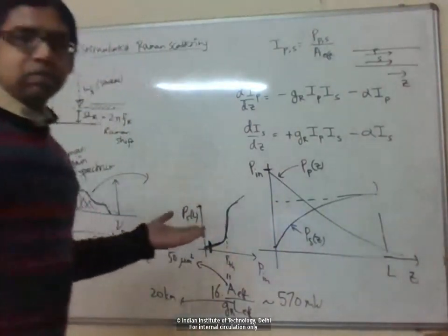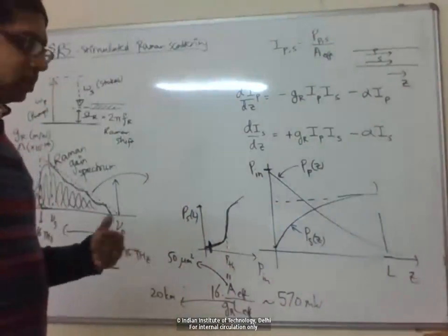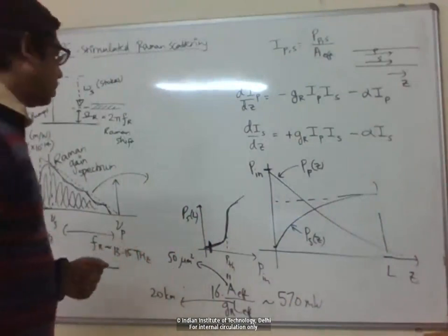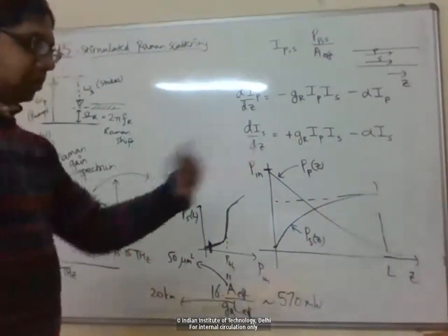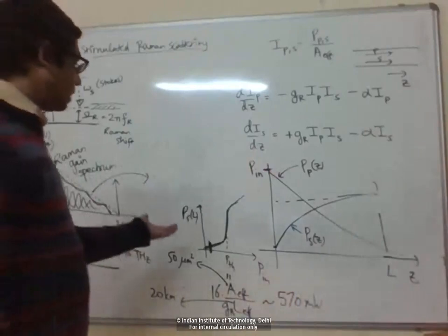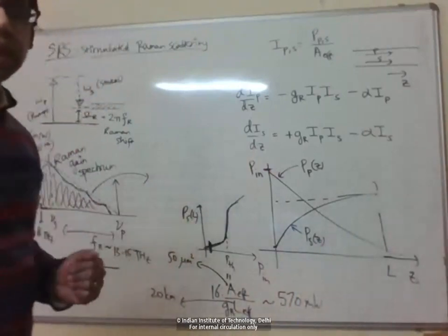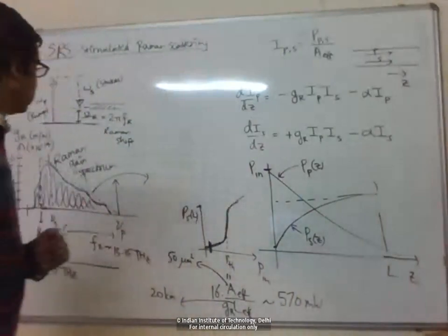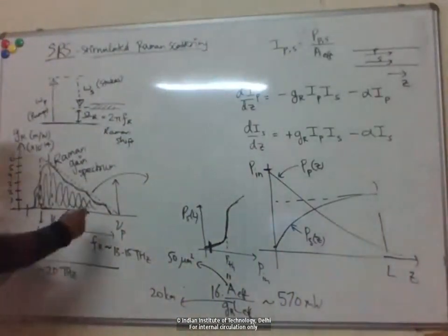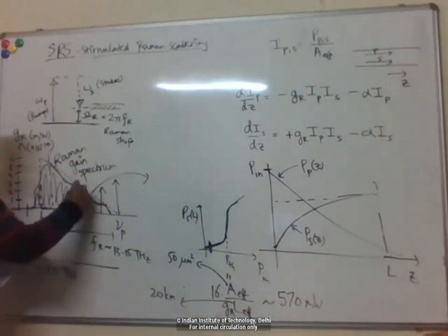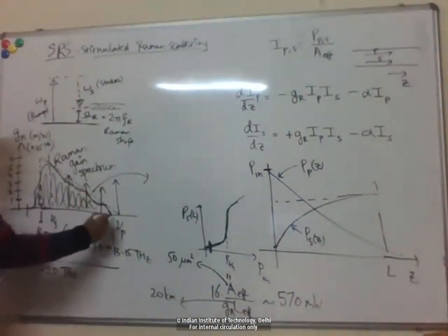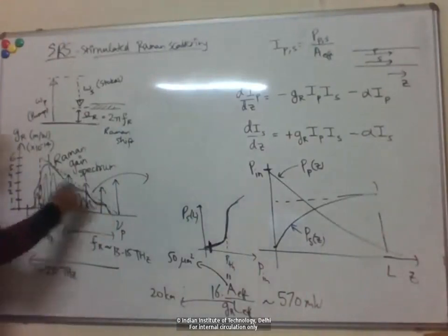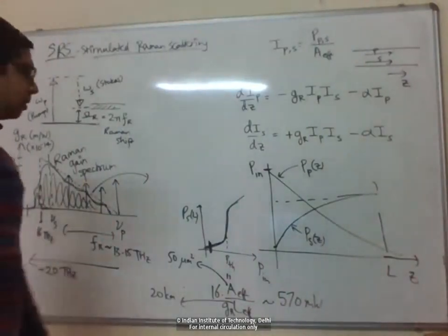So unlike, for example, the Brillouin case, where the Brillouin scattering acted on each channel individually, and there was no coupling between different wavelength channels, here we can see that for individual channels, the Raman scattering doesn't do much. But if you have multiple wavelength channels, so let's say you have some WDM now with multiple wavelength channels, all propagating through the fiber here, you can see all of them. Let's say they lie within this gain spectrum.